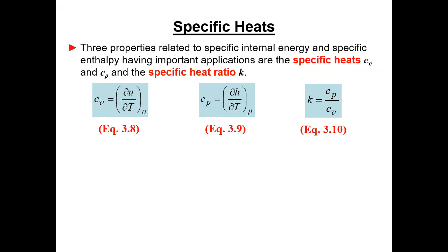A lot of times the change in internal energy doesn't change very much with respect to volume, and so you just forget about that, and you make that a derivative, and so then you've got CV is equal to du/dT, and then you can multiply across by dT, and then you can integrate to get a change in internal energy. And if CV is constant, which is fairly nice to assume a lot of times, if your temperature range isn't that great, you can assume it's constant.